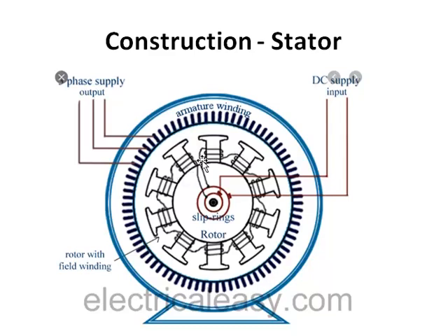When this rotor is rotated with external mechanical energy, all the armature winding conductors, which are static, will start cutting the magnetic flux. And we know that whenever the flux linked with a coil or conductor changes, an EMF is induced in all those conductors. The conductors are connected in three phases, so it will generate a three-phase output. That is how we get the three-phase output.